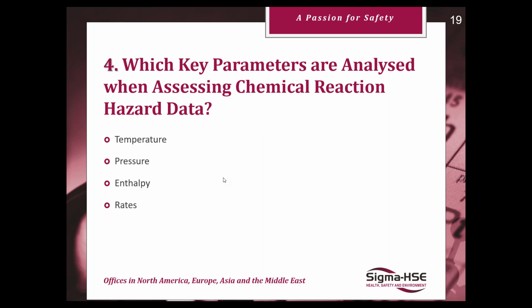This can help with R&D optimization steps. If you perform your reaction as you are intending to, and you match up the measured enthalpy against what you thought it might be from your literature calculations, and it doesn't really match, then maybe you're getting a low yield in that reaction, and you should look at, for example, your temperature set point or feed rates or what have you, or mixing agitation needs. So that's more about your desired reaction, but we can also look at enthalpy for decompositions.